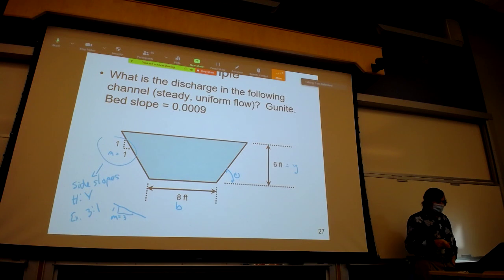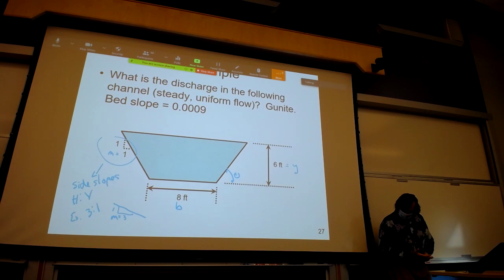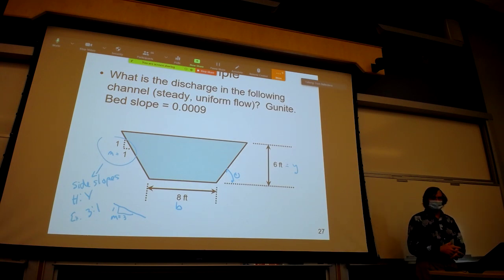So in this channel, it's lined with gunite. Gunite is just cement that's splattered onto the walls. So we were just doing a culvert lining project on I-89 up in Warner. Bartlett Brook was flowing through these 8-foot diameter corrugated metal pipes, and the bottoms had basically rusted out, and they were under 40 feet of fill. So they're not going to stop the traffic on the interstate to dig up that culvert and replace it. That's a really expensive project.